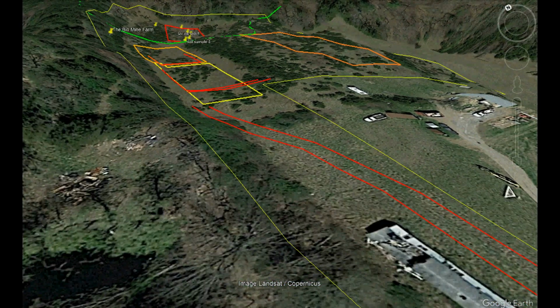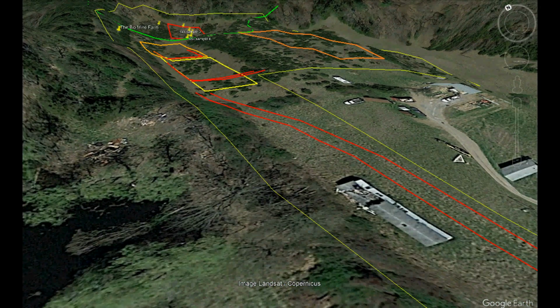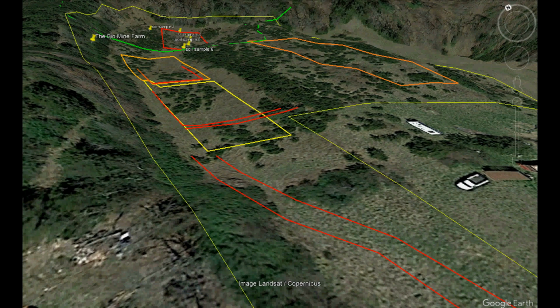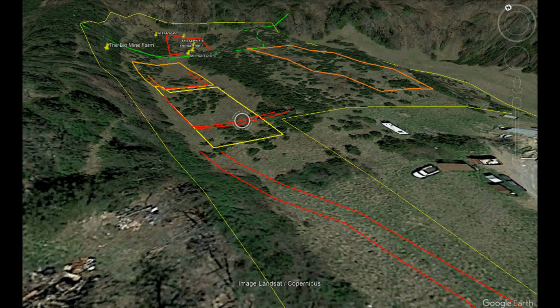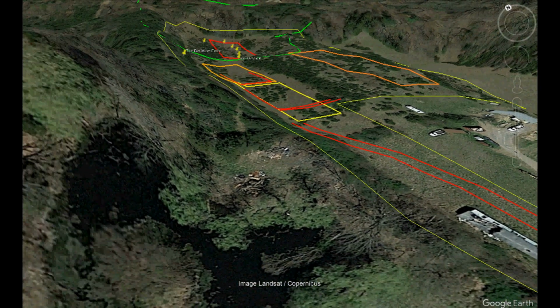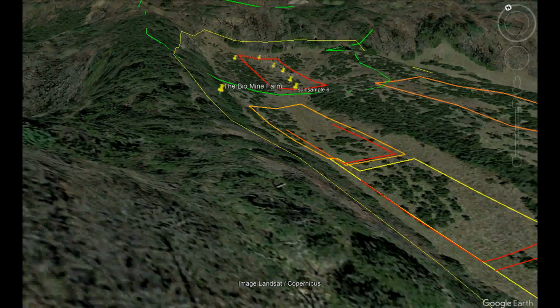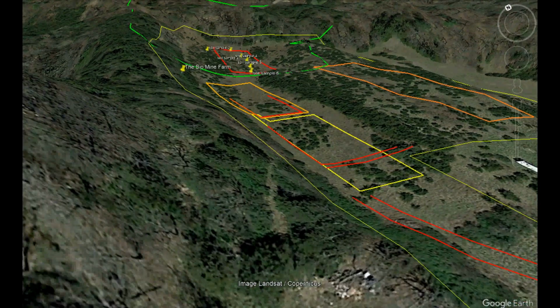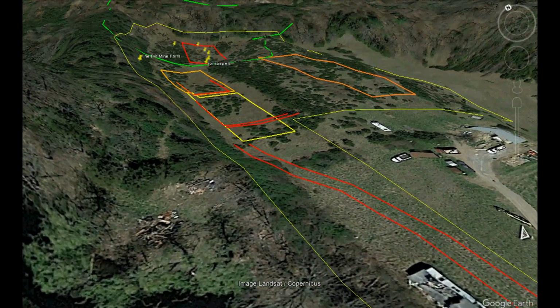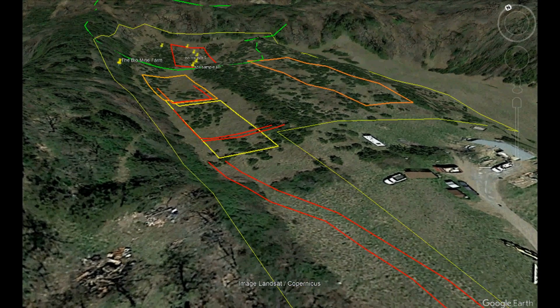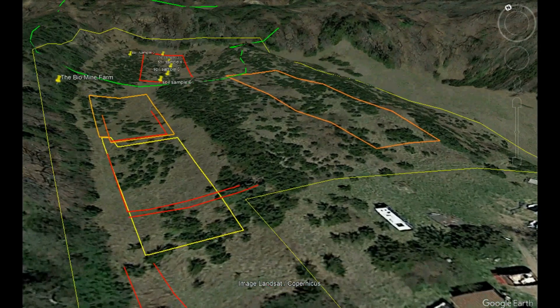Now, not too far away here is a pond. Allegedly, the bottom of our grow area sits at around 270 feet, and this pond sits at about 261. So theoretically, we could dig about a 12-foot deep hole here, or drive a sand point and pull water from that water reservoir. I'm quite sure when you look at the other terrain around here and swamps and the way that this terrain and slopes run, that there's plenty of water in that aquifer right beneath us if we need it. So that's one part of the perspective.